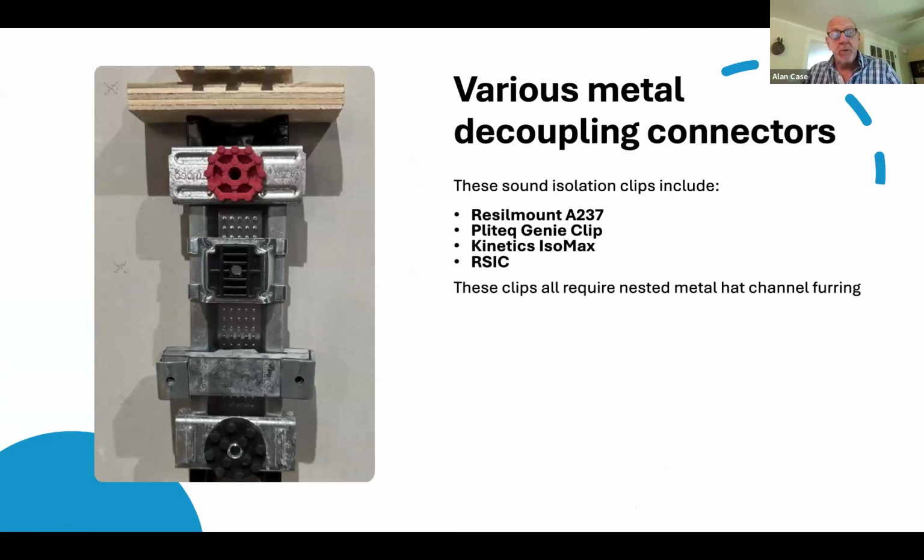There was a woman in Boston who spent $4 or $5 million on this gorgeous brownstone project where she was creating 3 condominiums, very high end, and to control noise, she was so paranoid that she had every floor joist cavity, every stud cavity, and even the rafters, everything shot and filled with rigid foam, and they basically had to go in and gut the building.